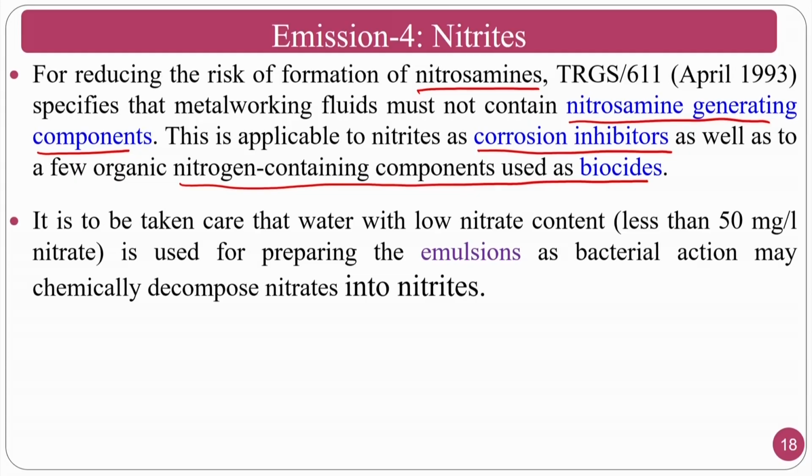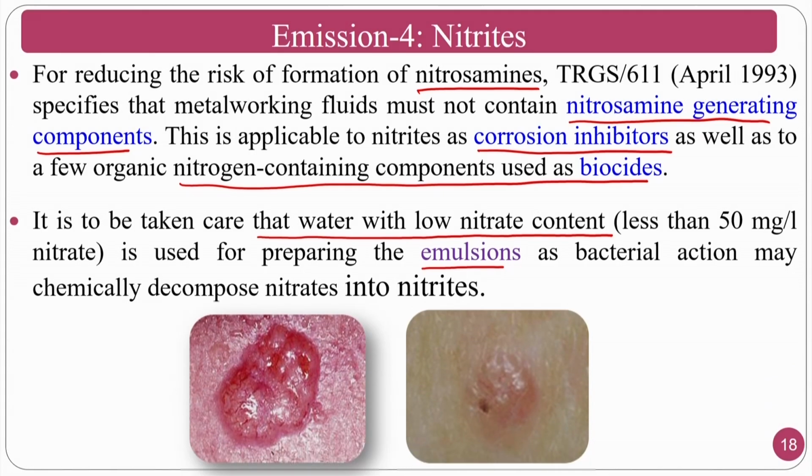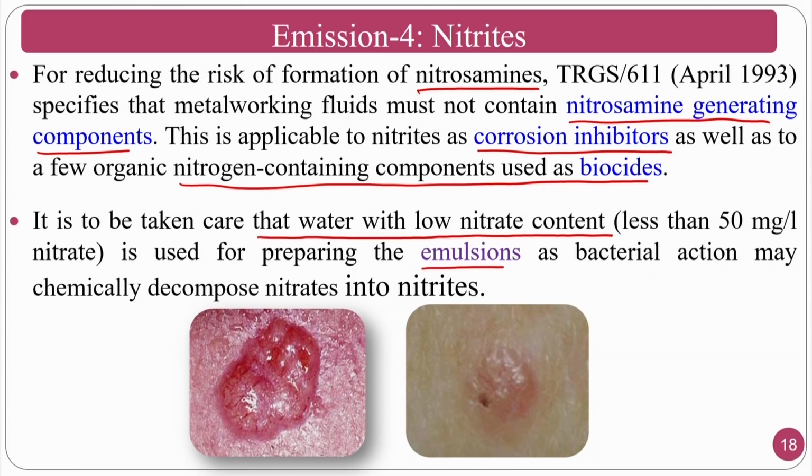If you can take care of that, it won't release the nitrites when you are applying it in the machining regime. Care should be taken that water with low nitrite content, less than 50 milligram per liter, is used for preparing the emulsions, as bacterial action may chemically decompose the nitrates into nitrites. As I said, this is carcinogenic. It causes skin cancer, mostly when it falls onto the skin of an operator.